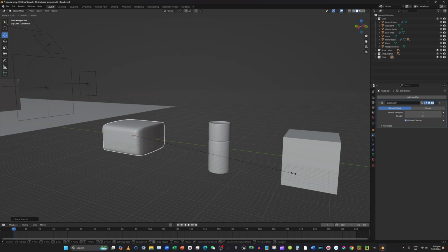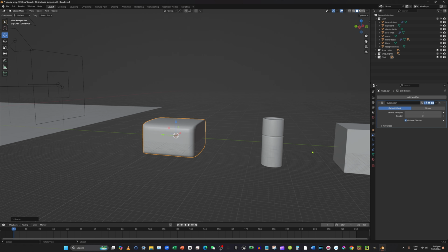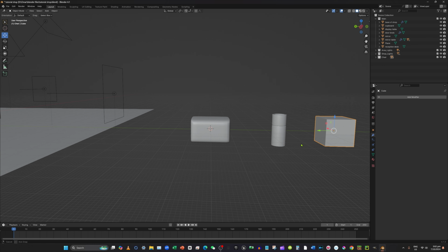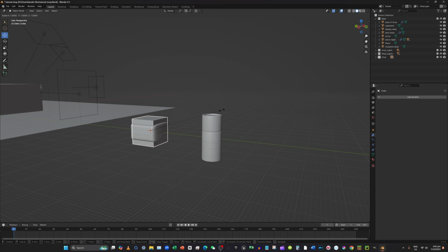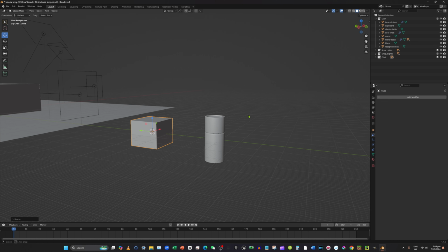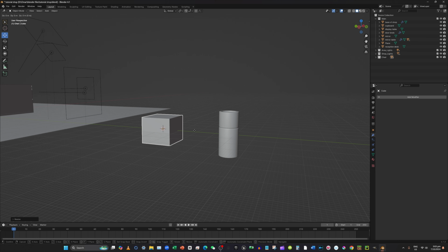Then we can go to object mode, shade smooth. Okay, scale it up a bit, just to size with the box. And then GY, move it here. I want to scale the slope down so it fits. Scale this up, and click the cube, SX to scale it on the x-axis, and then SY to scale it on the y-axis. Yeah, so it fits, so that's good.